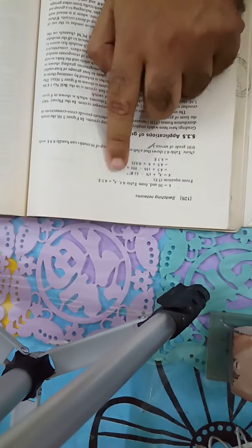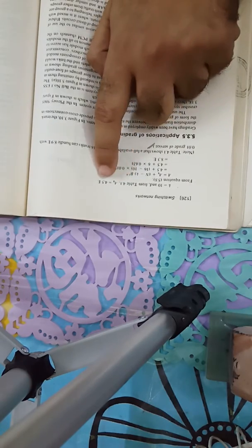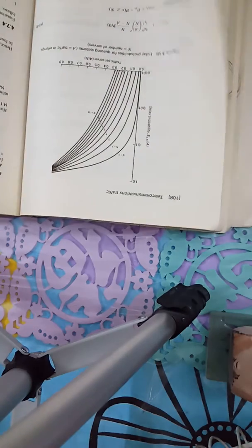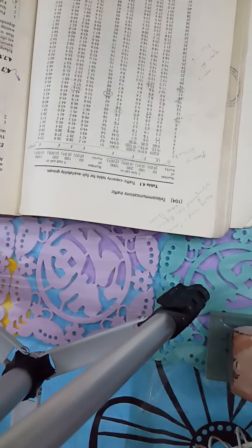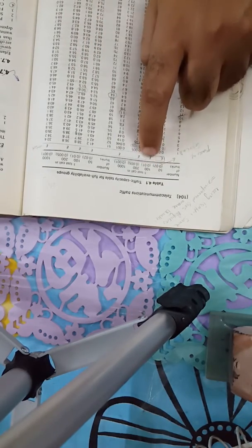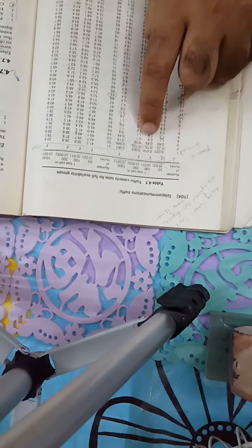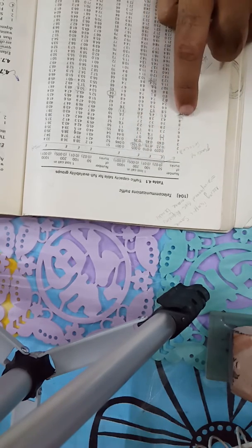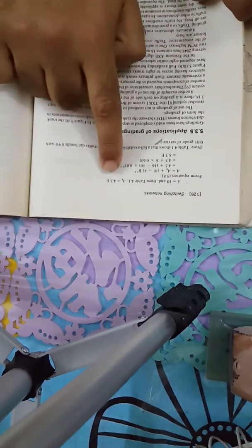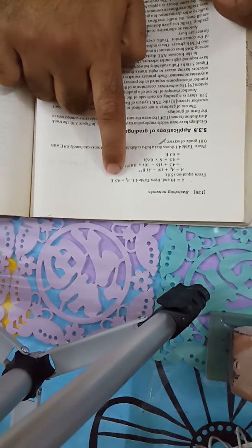Here k is equal to 10, which is the availability, and from equation 4.1, Ak is equal to 4.5 Erlangs. How did we find that out? Let's go to table 4.1. See the column for 0.01 grade of service, and for the number of trunks equal to 10, we have 4.5 Erlangs of traffic.